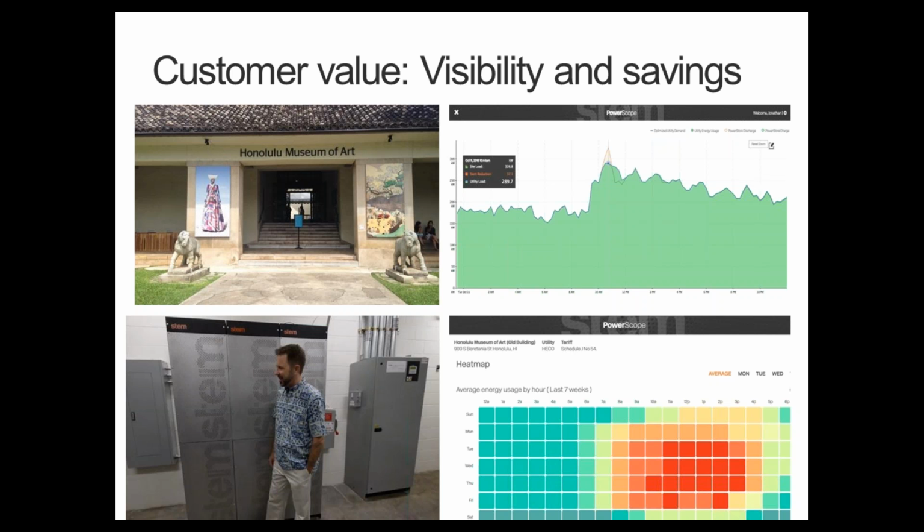For most customers, what we're doing is more, every month, that kind of peak shaving, and we're creating just a demand charge benefit. You see the Honolulu Museum of Art system there in the bottom left, and that's our modular system. We've got 56 of those towers out on Oahu now that make up the 1 megawatt project that I described. Each one of those towers is an 18 kilowatt 2-hour battery tower, modular tower. And then we show the customer their electricity usage, and we show them what the battery system is doing, and we try to empower them to make smart decisions.